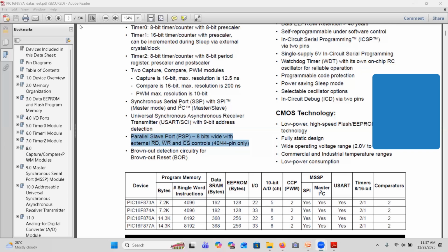Let me ask you the question in this way. When a project comes to the automotive engineer or an embedded engineer, it says you have to display ACC status in an LCD display or a TFT display. This is the requirement, right? If that is the case, the embedded engineer should immediately check how we can interface a display with a microcontroller, yes or no, right? Yes, sir. There are many methods. There are certain displays you can interface serially using SPI. There are certain displays where you can use the parallel slave port, PSP, method. Using that you can interface.